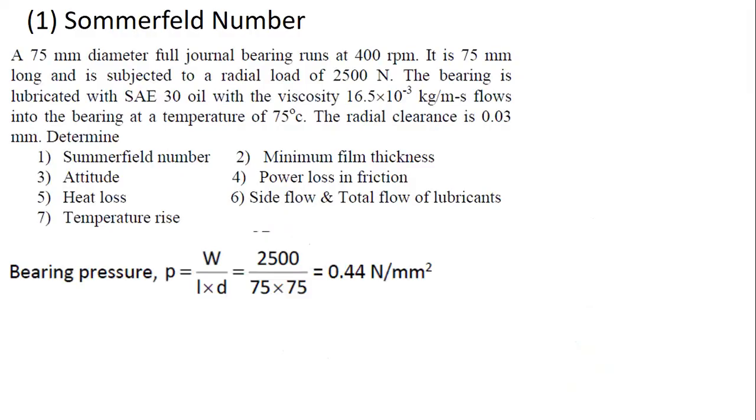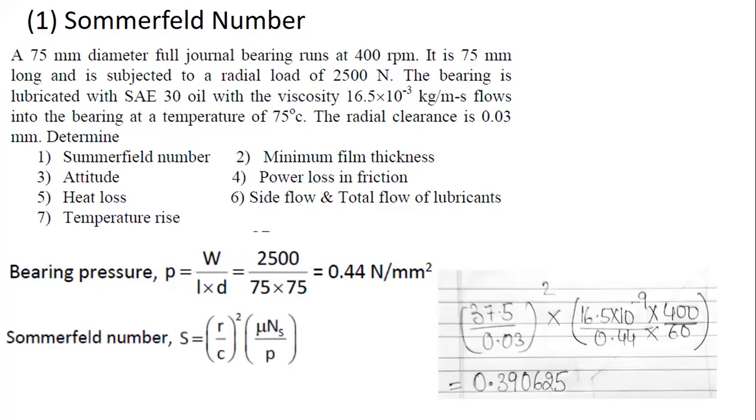So, like you see here, load is given, length is given, diameter of journal is given. So we found out pressure. On the basis of this pressure, we can find out Sommerfeld number, whose calculation I've done here.